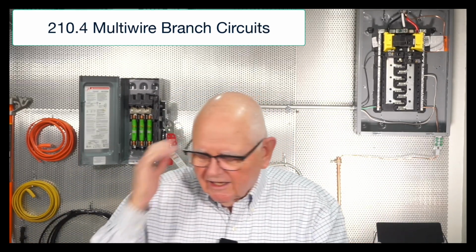I've run into that in three-phase systems, and probably some of you have as well in single-phase or three-phase systems. I had an instance where probably an inexperienced person, probably not an electrician, whatever, I was working on an injection molding machine, and I had power coming in, right? I had power from A phase and C phase from one panel board and power from B phase from another panel board. Well, that gets into another whole separate list of issues there in the code. But anyway, I always want to originate my conductors, obviously, from the same enclosure.